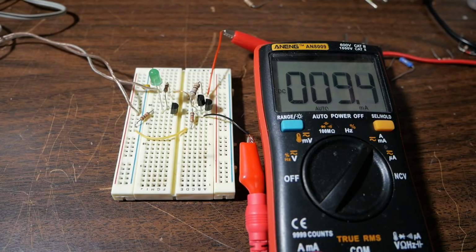So again, I will adjust the voltage going into the base and see how it affects it. So we're starting at 16 volts. I guess if you want to be technically accurate, it's minus 16 volts. We're using PNP transistors. And we're getting low, about 4 volts. And you can see it does drop quite a bit. Of course, if I turn it all the way down, it pretty much goes off.